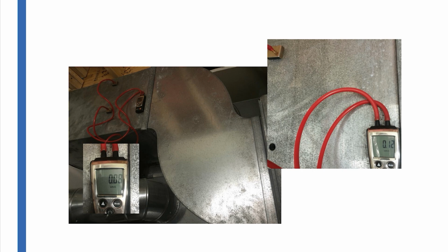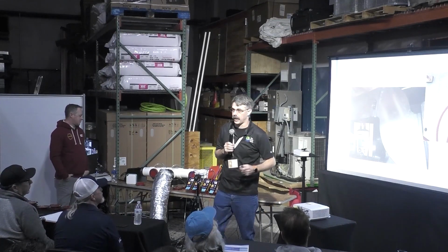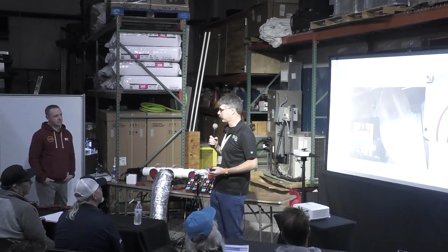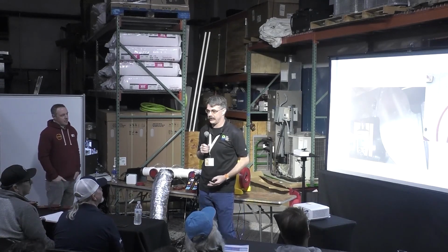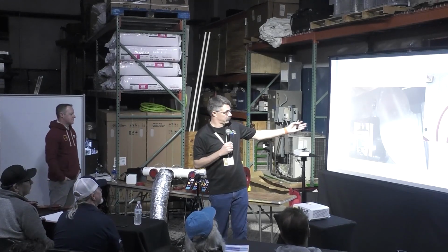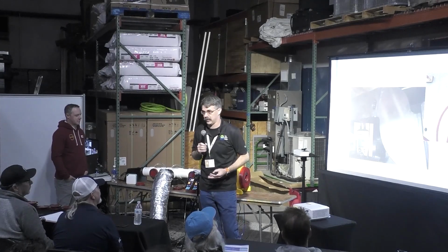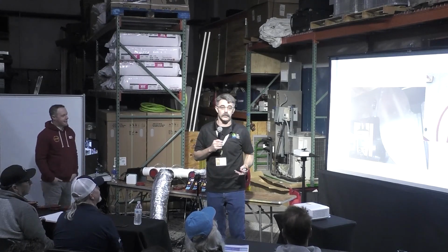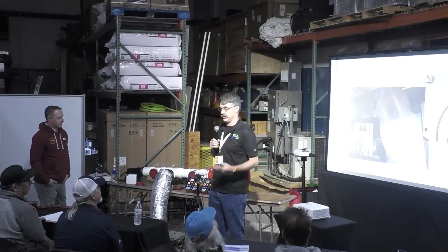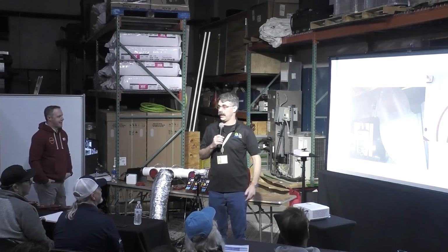And this is one of the things where unless you're testing, you're guessing, because a lot of people walked up to that and said, man, that's some really, really beautiful ductwork. It should work great. I've tested pretty duct systems that didn't work worth a darn, and I've tested some really ugly duct systems that actually performed well when you tested them and said, hey, the static pressure's low. I got airflow where I want it into my rooms.